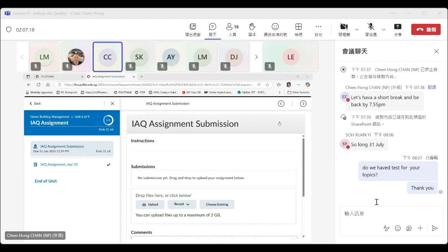So if the building has some kind of air well design, maybe at the center or at certain part that allows this smoke or hot gases to be vented up through like an air well, then you will realize that the ventilation will improve and the quality of the air in these spaces will be better. Right?